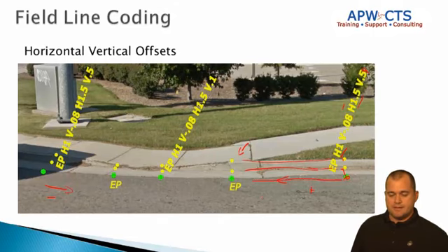Okay. Now when I get over here, I'm making a change to the vertical. All right, so this shot's the same, but this next one I got a 0.1. So I'm coming up just a little bit higher for that one. So what'll happen is this is going to drop down, okay, and then this will come over here. So it's going to create my curb depression. Again, using the same codes for this one, so I just need an EP there.